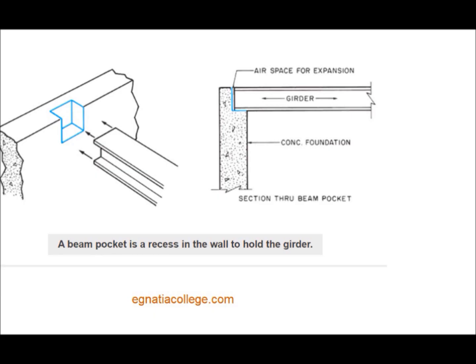It is important, however, to get the masonry opening size from the window manufacturer before forming the opening in the foundation wall. The masonry opening is the size of the opening required in the foundation wall to accommodate the window. This size may be different from the nominal size given in a note on the foundation plan.